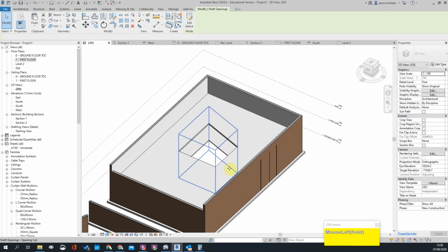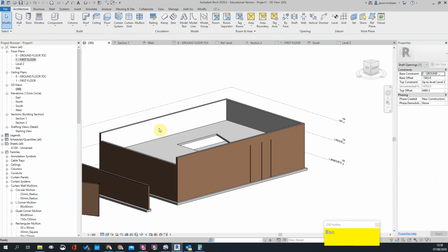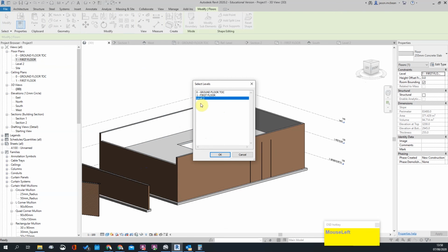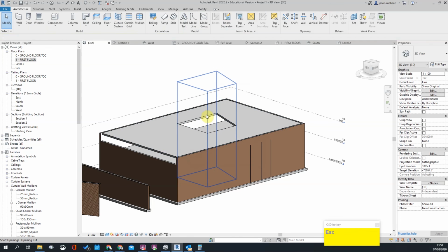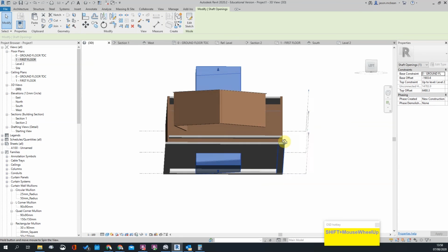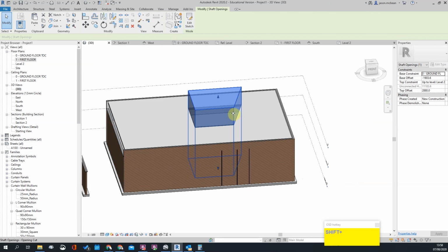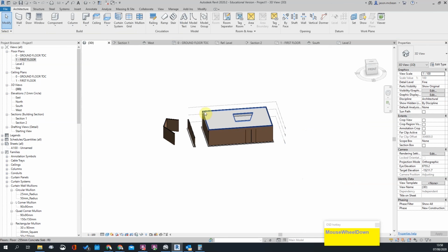Okay. So that's the beauty. So if I duplicate this floor slab, copy, paste on level 1, for example, line to this level 2, and because the shaft is going through, it'll keep penetrating that for me. Okay. All right. So that's that in a nutshell.